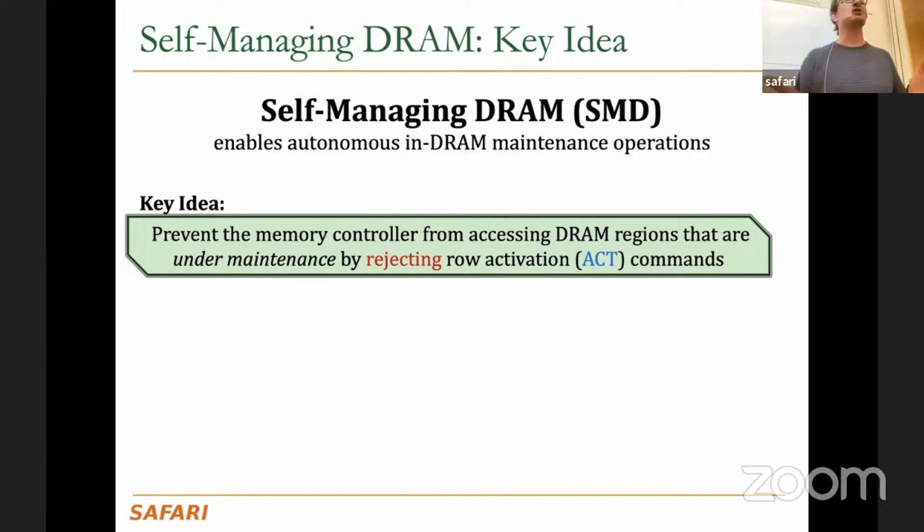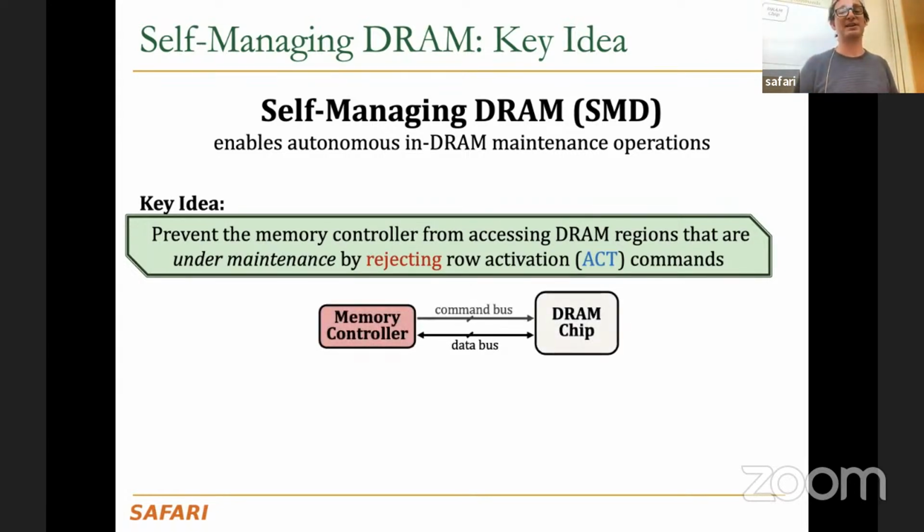This way, the memory controller doesn't need to tell DRAM to refresh. DRAM decides what to refresh, when to refresh, based on the characteristics of the cells, based on whatever it thinks is useful. And hopefully, it keeps the refresh of a particular region that it locks very quick, and the memory controller hopefully doesn't even access that region while the DRAM is refreshing it, right? Otherwise, the memory controller needs to send refresh commands periodically, essentially today, right?